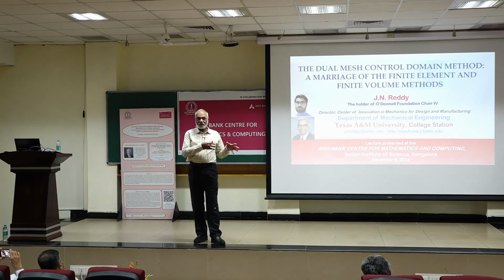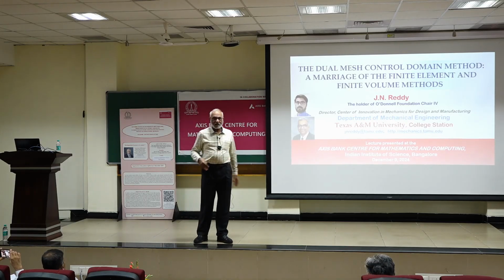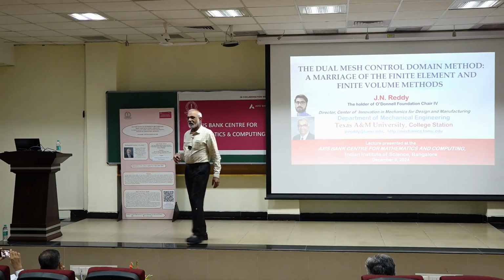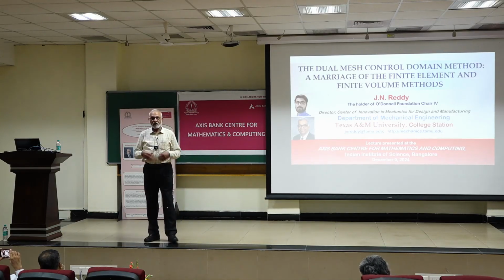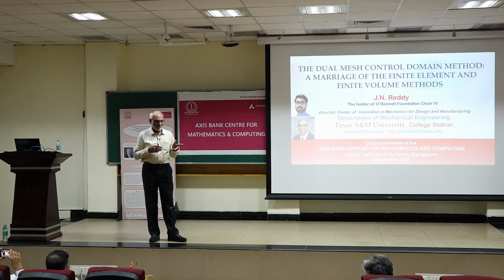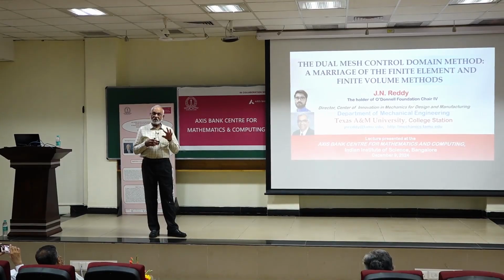Whereas in finite difference, you go straight to the differential equation and replace the derivatives with finite difference Taylor series formulas. So neither one has any way of minimizing the error, whereas finite elements is based on such a concept: minimize.